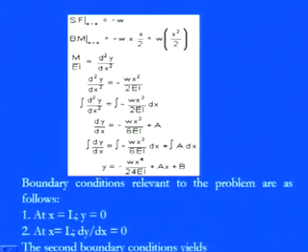So now again we need to follow the same condition here, the slope and the deflection at the rigid point, that means at x equals L, which is always 0. So here the slope equation is minus Wx cube by 6EI plus a. If you put x equals L, the value of a will come, and we have the deflection term, minus Wx4 by 24EI plus ax plus b. At x equals L, dy by dx is 0 and y equals 0 as well. So for those conditions we can get the values of a and b correspondingly.